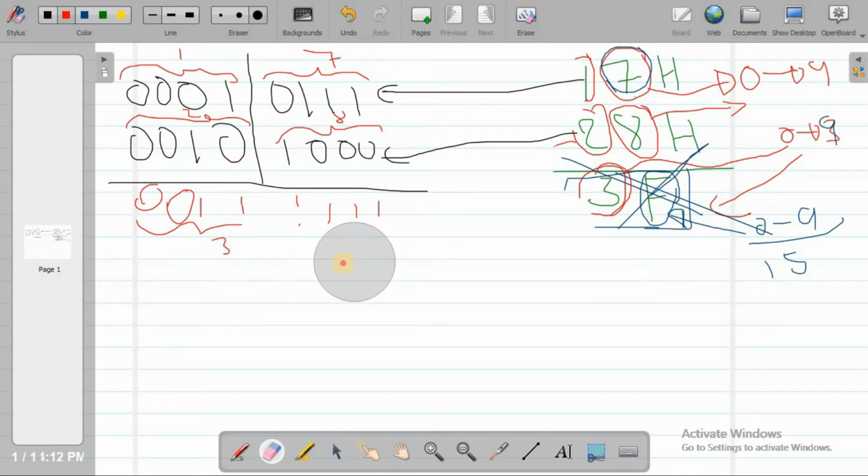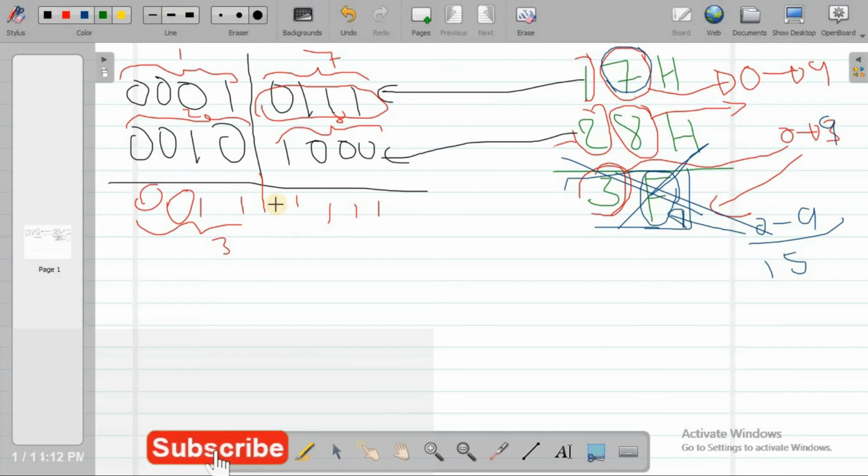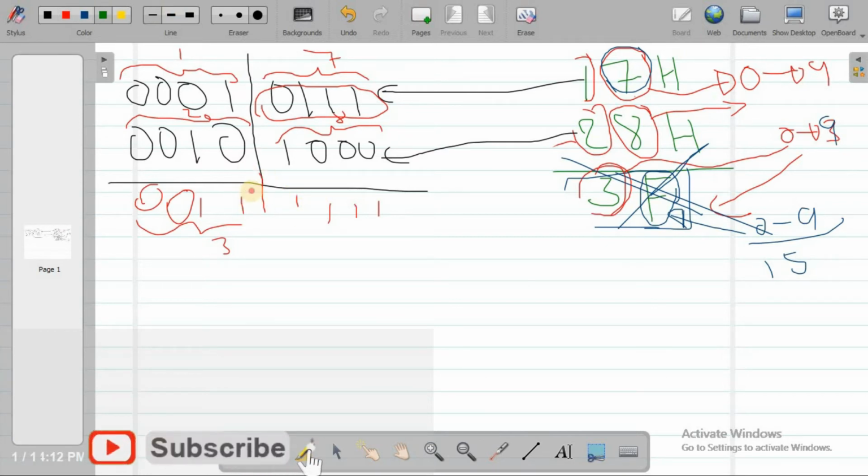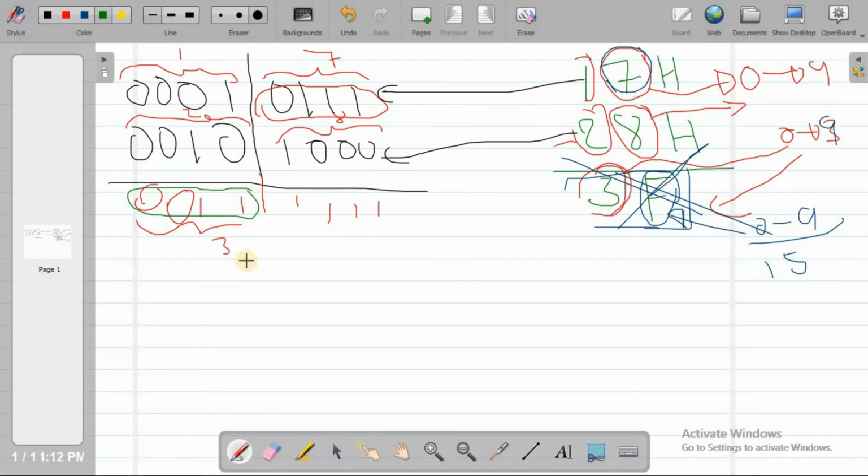In BCD, to fix the result when we add two BCD numbers and realize the result is not a BCD number, we add 6 to the 4-bit nibble that has the problem. If the upper 4 bits were greater than 9, we would add 6 there to solve that result.